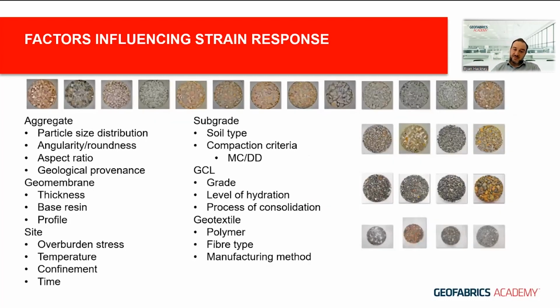There are lots of factors that influence that strain response, as I mentioned earlier. With the aggregate, there's the particle size distribution, the angularity or its roundness, and the rock aspect ratio, so something that's a lot longer than it is wide has an influence compared to something with a good 1-to-1 ratio. The geological provenance, so something that may split during the test might have sharper edges, can influence. The membrane type, its thickness, its base resin, its profile, whether it's structured or not,